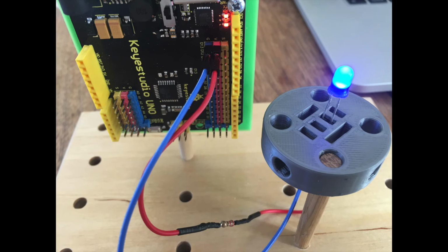If your light does not come on, check to see that your LED is turned the correct way with the long leg in the V wire and the short leg in the G wire. Also check your connections. If your light still does not come on, switch LEDs to see if the light is burned out.